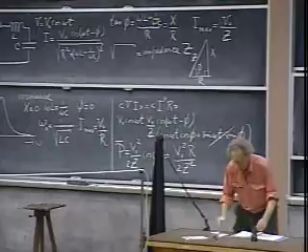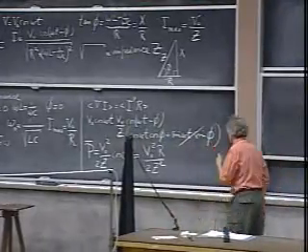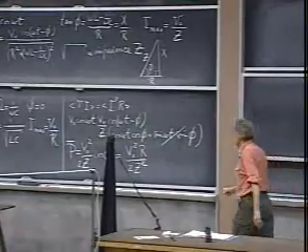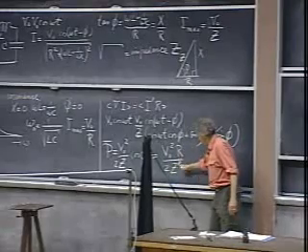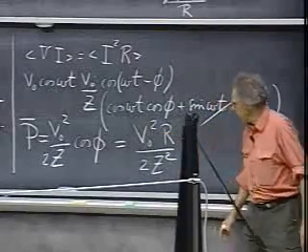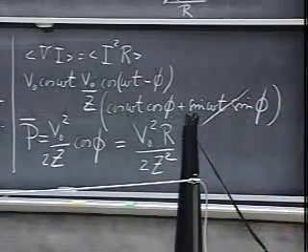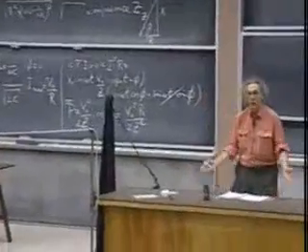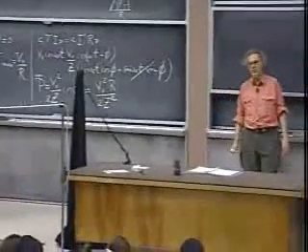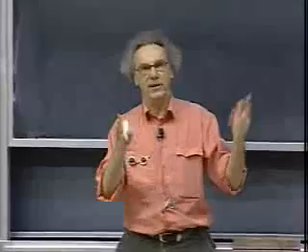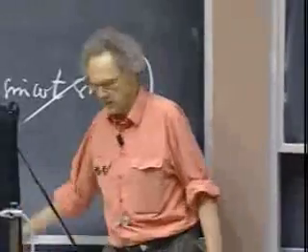So now we can look at resonance. It's always a very special situation. When we are at resonance, Z equals R. So you replace this capital Z by R, and then you find V0 squared divided by 2R. That's utterly trivial. You could have predicted that. It's really Ohm's law staring you in the face. There is no self-inductance and there is no capacitor at resonance, so you might as well have treated it as a simple system only with R, and you find immediately then that answer.